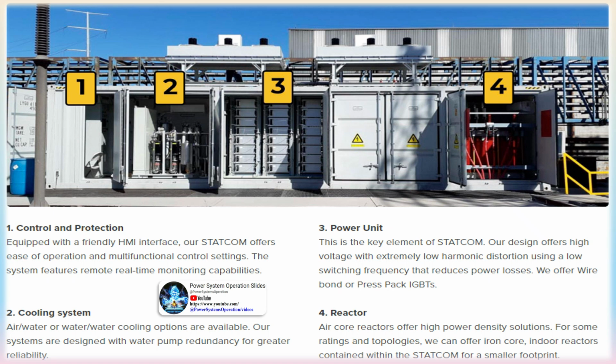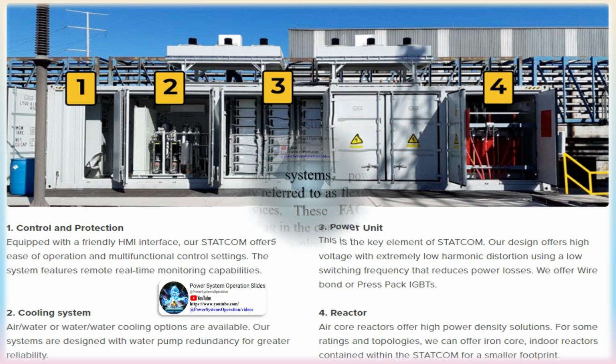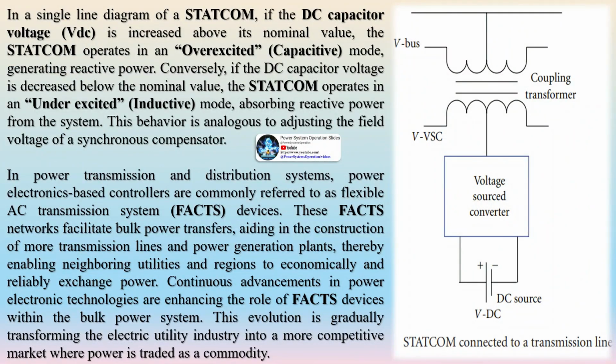Utility providers need to implement local control measures to address various potential issues such as uneven power flow, transient instability, subsynchronous oscillations, and dynamic overvoltages and undervoltages. Among these, multi-level converter-based FACTS devices offer improved power quality, reduced switching frequencies, decreased power losses, and minimized stress on individual power electronics components. Additionally, these devices enable more effective use of battery energy storage systems (BESS).